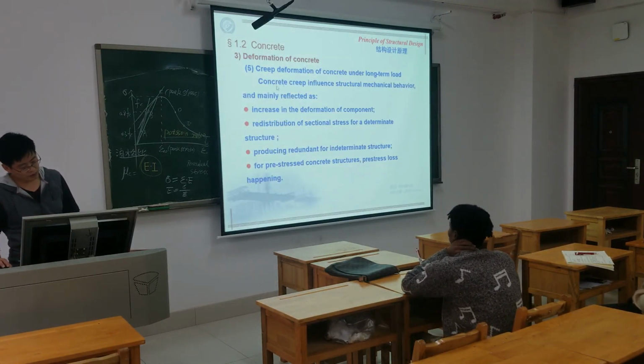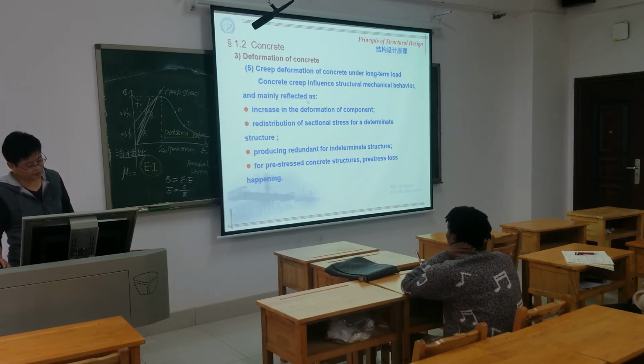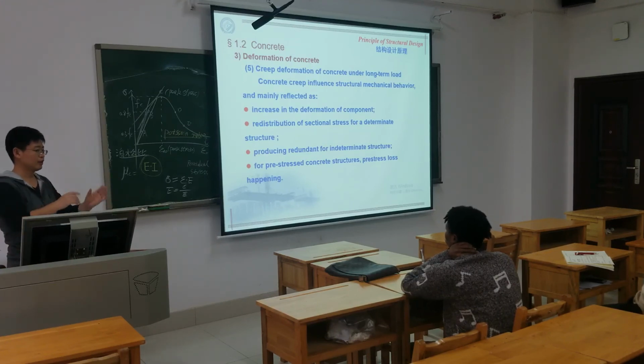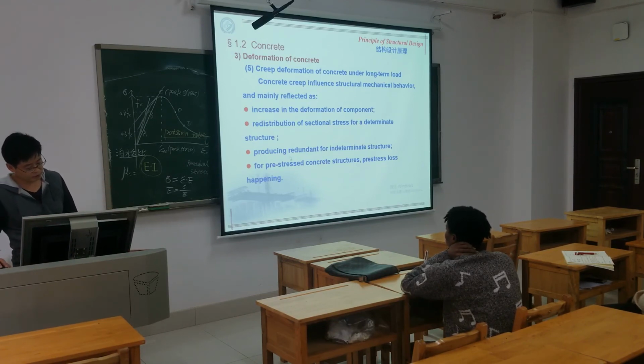Concrete creep influences structural mechanical behavior, mainly reflected as an increase in deformation and the redistribution of the secondary stress for the statically indeterminate structure. Because the deformation is changing, the stress will be redistributed, producing redundant forces in the structure.